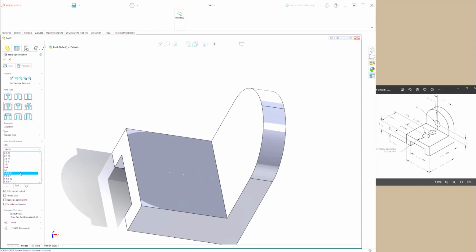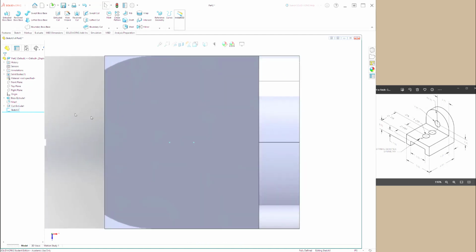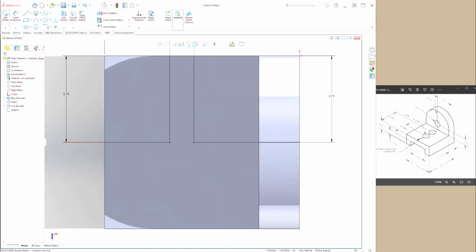It will give me the ability to do 1.25 or 1 1/4 inch 12 threads or 1 1/4 inch 7 threads per inch, but that's not what we're looking for here. So since that's not the option, we're going to have to go to Plan B, and Plan B is to go back to our sketch. So we'll edit the sketch by right mouse clicking, and with the points we'll draw 2 circles. And what we're going to find out is that we got a problem.